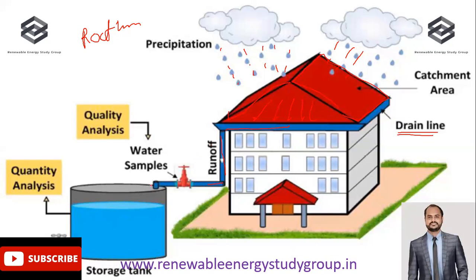But while we are giving this water to the storage tank, we need to use a filter in the system. The role of the filter is to remove the excess contaminants from the system and give the proper amount of water before any contaminant can be included in it. That is why we get quite pure water. But further, we also have to purify this water if we want to use it for drinking, while if you are using this water for gardening or any other washing purpose, we don't require any RO system to be designed in this rainwater harvesting system.